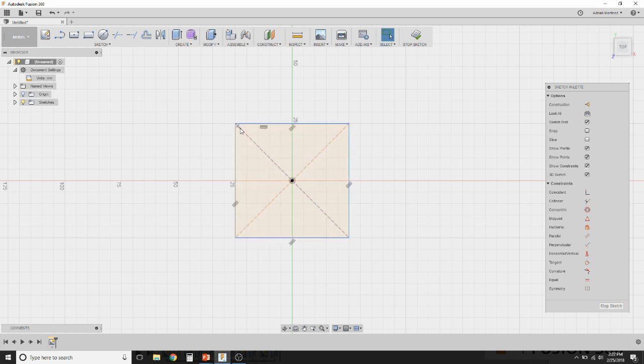And then this particular constraint means that this is always going to be a perpendicular relationship. And these are all different constraints. You can hide them by clicking the Show Constraints checkbox off, and you can bring them back just by clicking it on. Sometimes after you've drawn a drawing with a lot of lines and a lot of complexity in a sketch, it'll get a little bit cluttered, so you can turn the constraints off to do that.